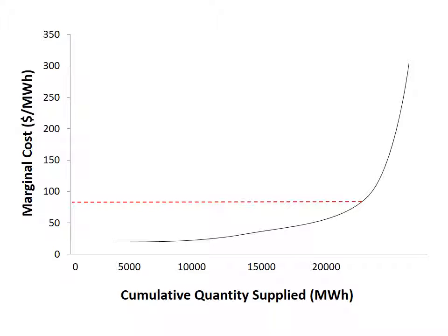So this discrete representation of the system supply curve can more or less be translated into what we would normally think of as the shape of a system supply curve. And for demand, we have very little price elasticity of demand, right? What that means is that when we are making decisions about when we use electricity as consumers, price really doesn't factor into it, at least any sort of sense of a dynamic price.